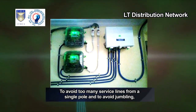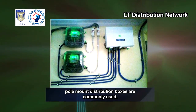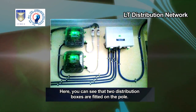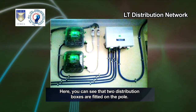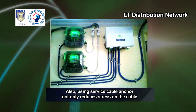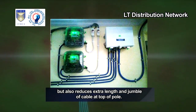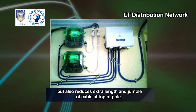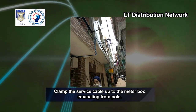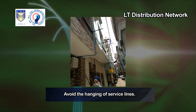To avoid many service lines from a single pole and to avoid jumbling, pole mount distribution boxes are commonly used. Here you can see that 2 distribution boxes are fitted on the pole. Also, using a service cable anchor not only reduces stress on the cable but also reduces extra length and jumble of cable at the top of the pole. Clamp the service cable up to the meter box emanating from the pole. Avoid the hanging of service lines.